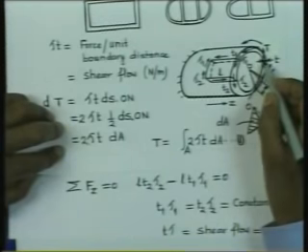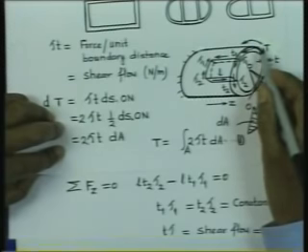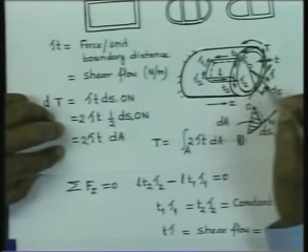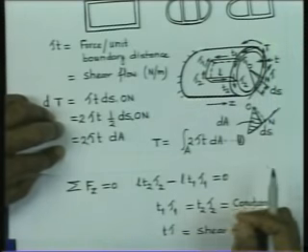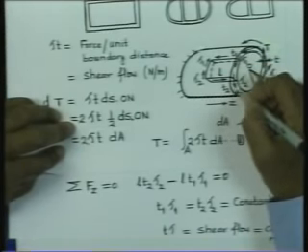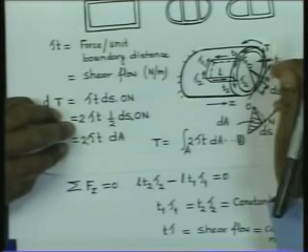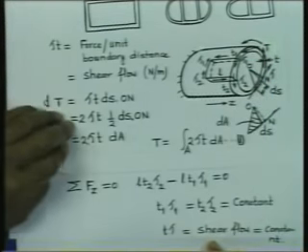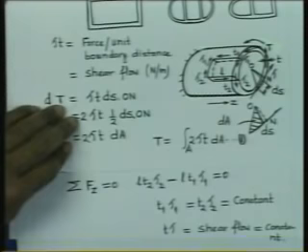Think of fluid flowing in the circumferential direction. If the fluid is incompressible, then every section would have the same quantity of fluid, and therefore, this shear flow is borrowed from that analogy, that some quantity of fluid is flowing and that fluid quantity remains constant, and therefore, this shear flow is constant. So, it is borrowed from fluid mechanics.